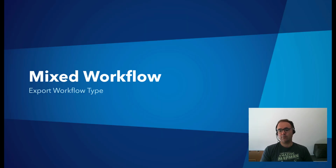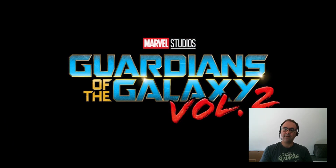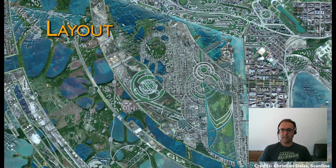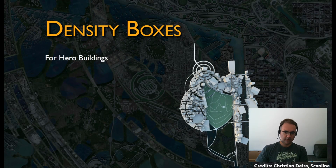Finally, we have the mixed workflow, which is the most versatile one. For example, in Guardians of the Galaxy, Scanline first used CityEngine to lay out the streets and then used pre-modeled building assets with 4 levels of detail to design the density of the city. So for the hero part of the city, they just used the lowest LOD, basically boxes, to design the density, and then the pipeline replaced them with hero assets.